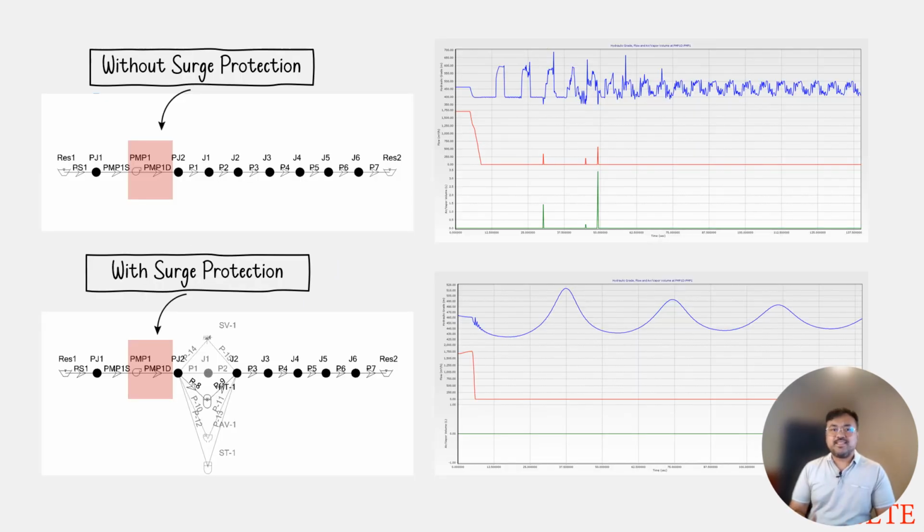So here is an example of how we can do integration testing in transient analysis. We set up time history and locate a point in the system where you want to see the pressure behavior at that point. In this case, we use the location from pump 1 to pump 1 discharge. Then we run the simulations using both protected and unprotected.